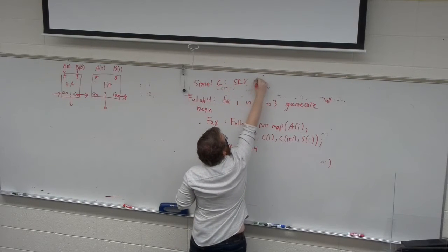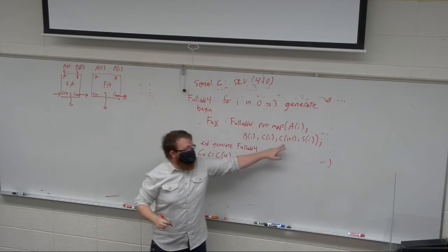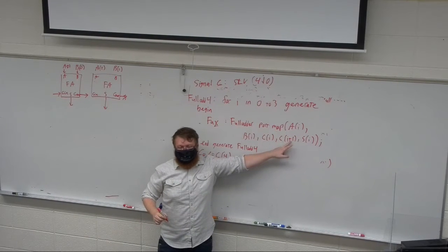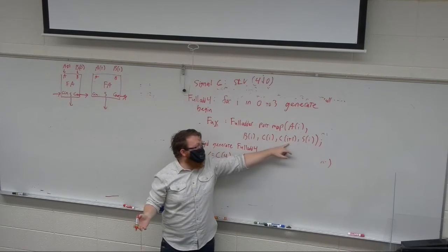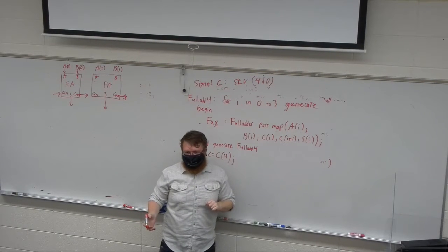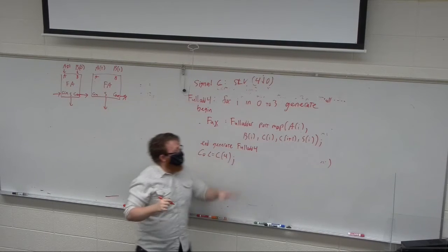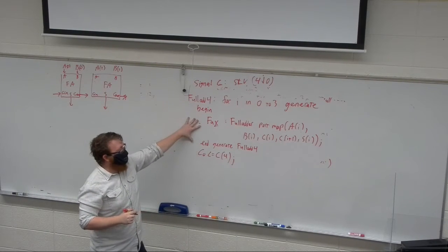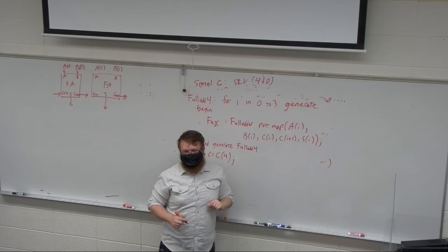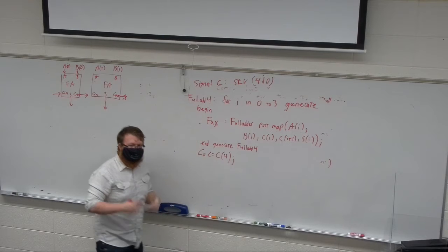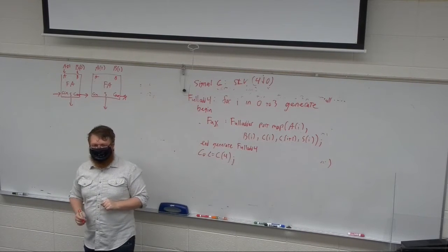A std_logic_vector, right? Because it needs to have more than one bit. So the carry in we're going to initialize to 0 unless we want to do something with it. Then every other one is going to take whatever the carry is and stitch them together for us. So instead of copying and pasting and then updating all of these, this generate is going to create the 0 to 3 full adders that are connected together one by one for us.